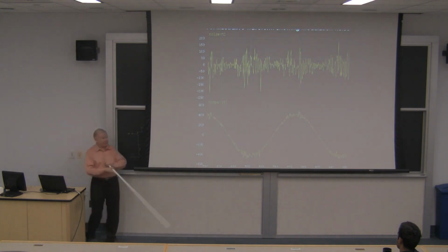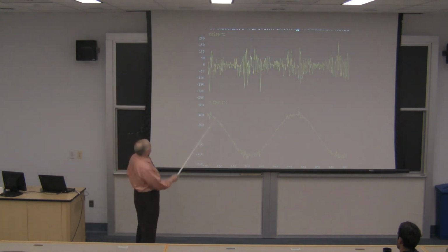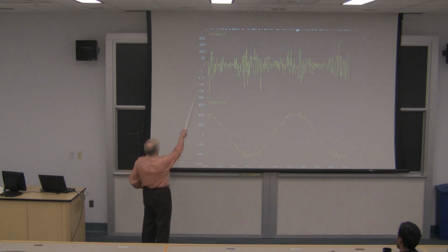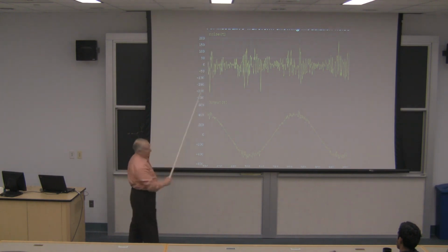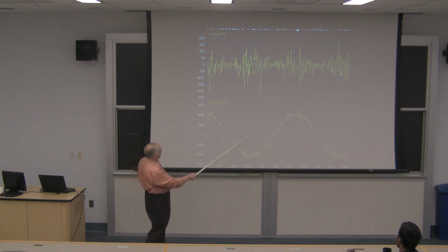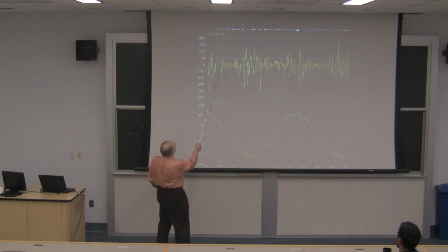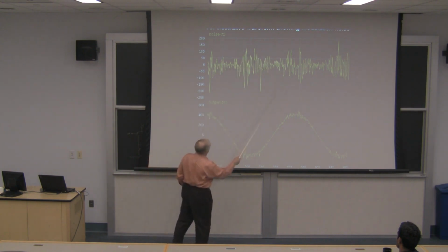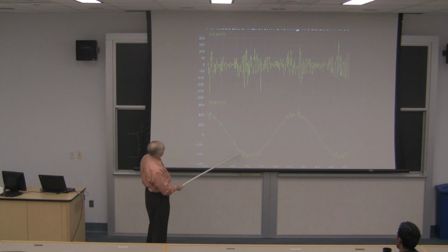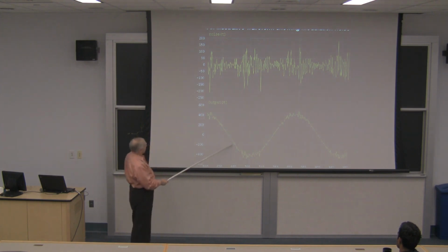So here's the sort of thing I'm showing. I'm sorry we've lost the title, but this is the noise versus time using TNT. And this is the output of some amplifier that's supposed to be perfectly sinusoidal. And what you can see, you can just about see it here, the noise is varying depending upon the amplitude of the signal. It's easy to see it on this picture, where all I've done is taken the output and added that noise vector to it.